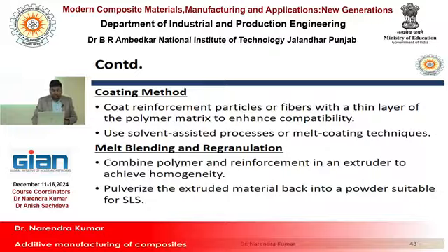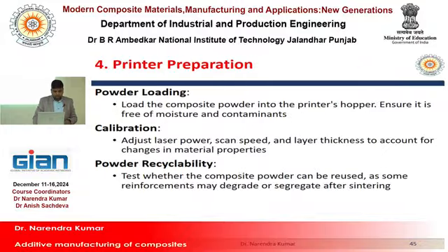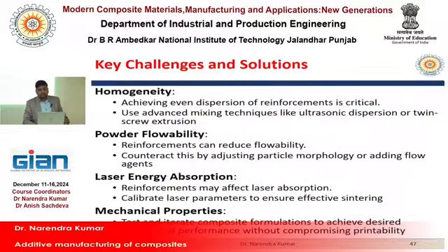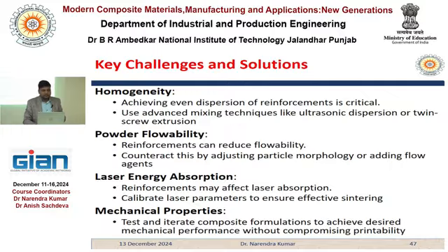Then particle size, flowability, and thermal behavior optimization can be done. So key challenges are homogeneity, achieving even dispersion of the reinforcement in the powder matrix, powder flowability, and laser energy absorption. So these are the challenges that may occur during composite development through SLS.